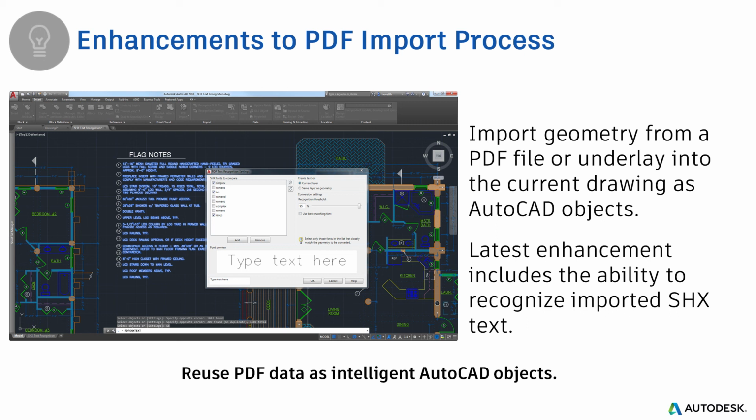So I have a PDF import file, and importing that, there's a number of SHX type fonts in it that aren't recognized. They're recognized as lines, circles, and arcs within the drawing. So I show the new feature we added in 2017.1, where you could select that text and convert it to MText. The thing that I show at the very end is the new part of the feature for 2018 is where we have what we call our best matching font.